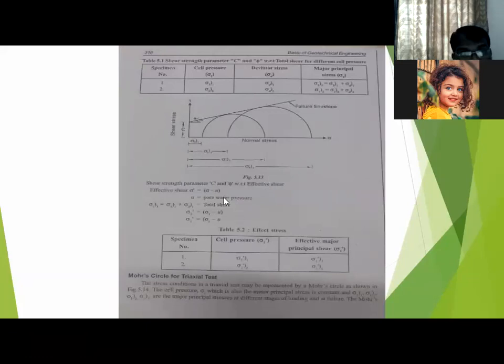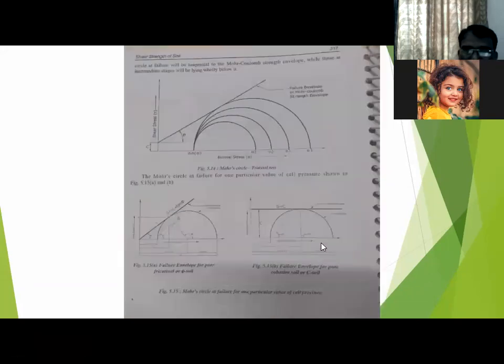And when the pore water pressure is also considered separately, then also we take this after the confining pressure. When considered combined it is like this, but when we take it separately, it becomes this. So this is the general Mohr circle. This is C, this is phi.